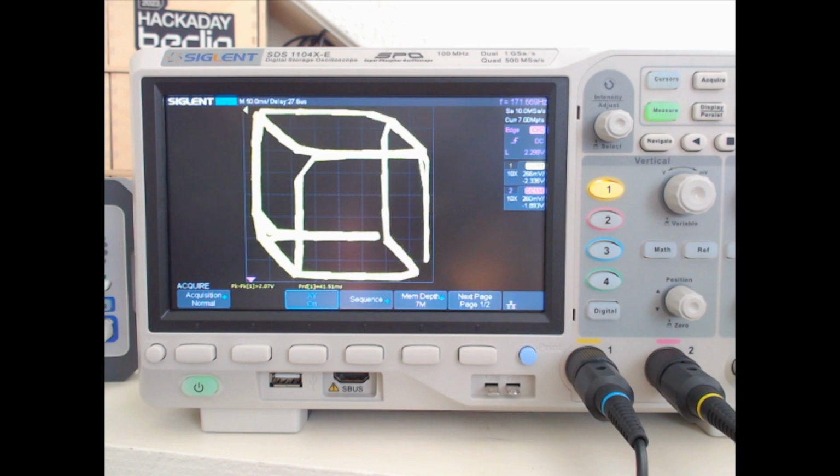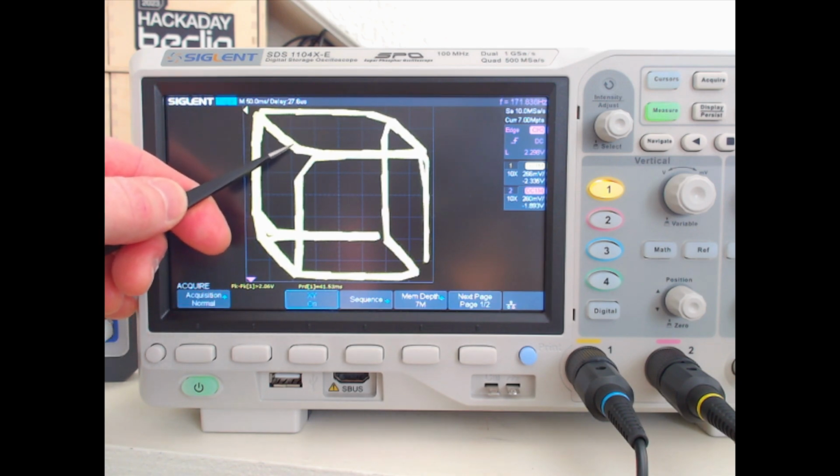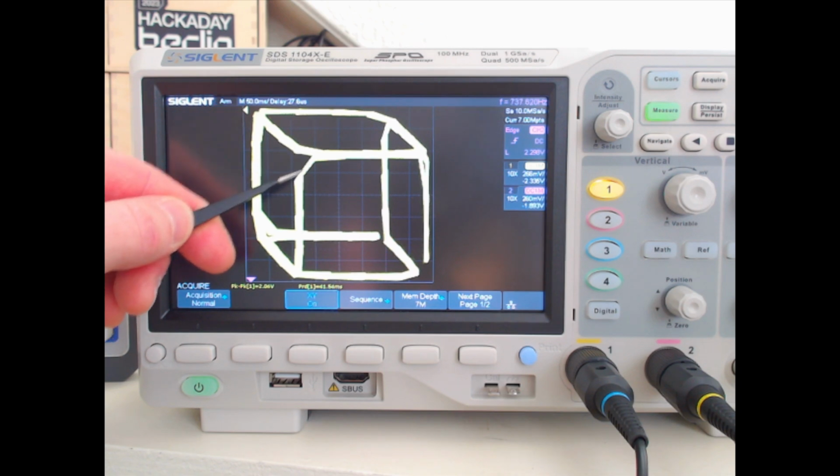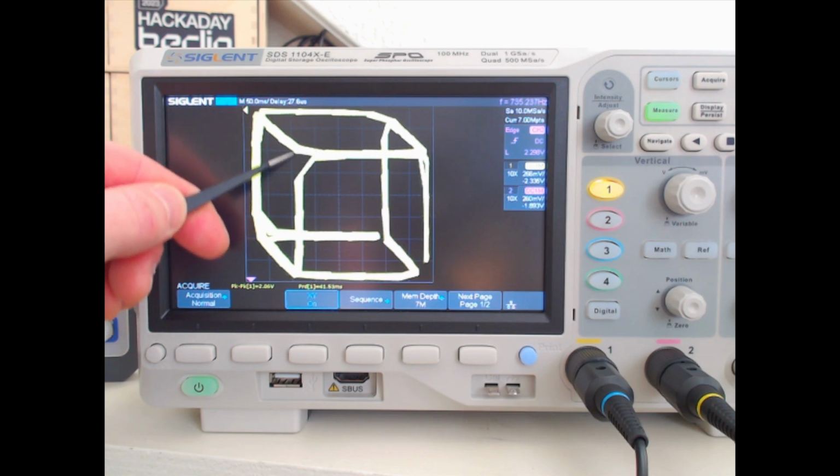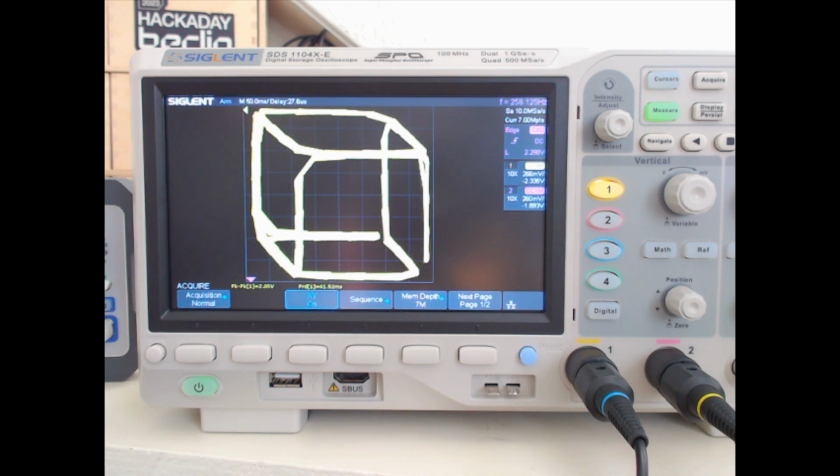And I think what's happening there is actually that during the normalization and then the scaling up process, and then the truncation from a floating point number to an int, we're losing quite a bit of resolution. And that combined with the fact that we only actually have 256 distinct voltage levels means that instead of coming up to this next point and rounding up to be here, we're rounding up to the last point, and then we're already jumping over here before where we should be jumping from here. And I think that's the main problem.